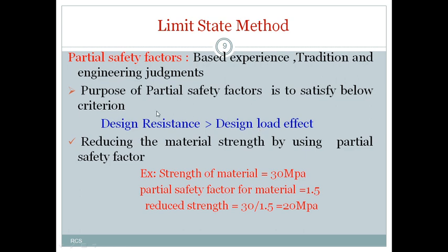What do you mean by this? Say, if you take any material and apply a load over it, it has resistance to deformation because of the effect of the load. That resistance is always greater than the design effect, or always greater than the effect of the load which is coming onto the structure. Right? These partial safety factors are also used to reduce the material strength. Why should we reduce the material strength?